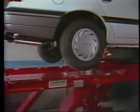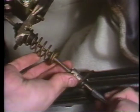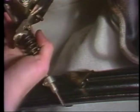When a vehicle with a pressure control valve is on a lift with the rear wheels hanging, it'll be difficult, if not impossible, to bleed the rear wheels. You must first disconnect the valve arm from the axle or support the rear axle assembly before bleeding the rear brakes.